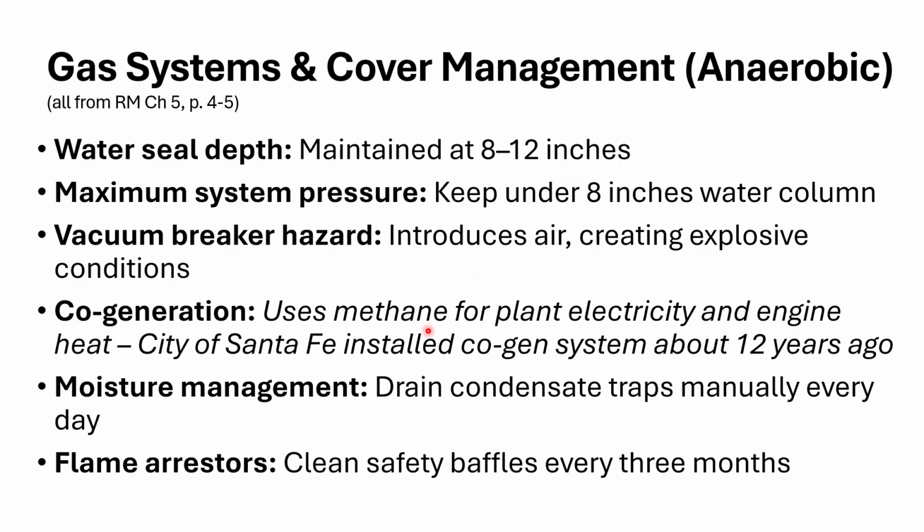And the methane that's collected can be piped off. We want it, of course, to be free of the condensate. That's why we have that set of surfaces to collect condensate and send it off to the condensate drain. So we want a moisture-free methane, collect it, and we can use that to heat up our heat exchanger, or as I mentioned, some places are putting in a combustion generator where they're burning that methane gas, using it to power a generator to produce electricity to run their wastewater plant.